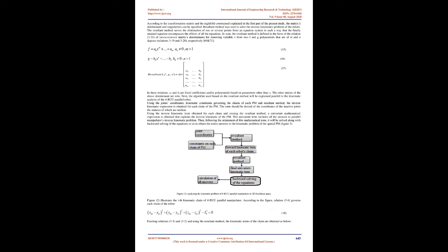The length of the mobile platform from point P of reference point 1 to point Ci is defined as B. If the Bi-Ci link's length is defined by a value equal to R, the point coordinates of Ci in the mobile reference would be given. It can be concluded from the analysis that the 4 design parameters, A, B, L and R, and 4 joint variables, θ1, θ2, θ3 and θ4, control the movements of the 4RUU parallel manipulator. 3.1.2 Geometrical constraints.